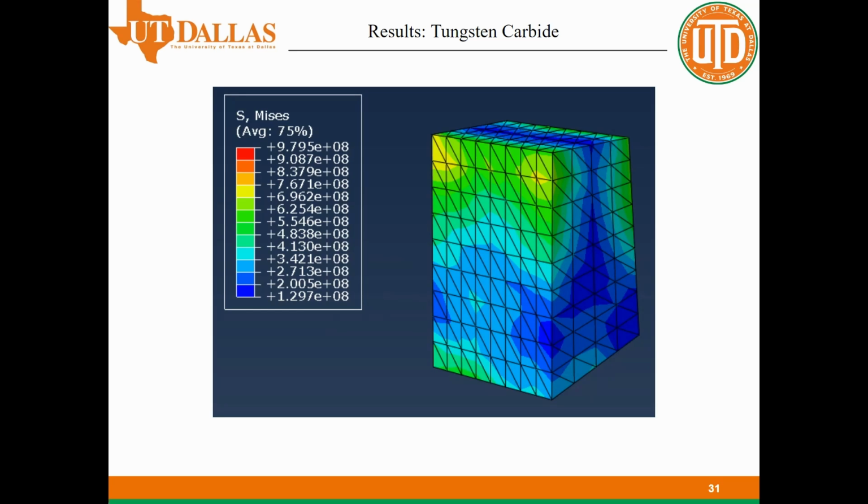Stress at the cutting edge is 270 to 600 megapascals, while tungsten carbide has an absurd flexural strength of around 1800 megapascals. This gives it a minimum safety factor of 3, and it's the only material we tested to convincingly withstand its cutting force.